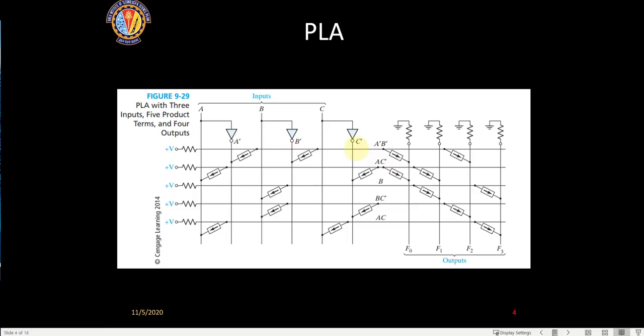So aren't the NOT gates supposed to be single direction flow, and the current can't flow in the opposite direction back towards A? Like, the current can't drop across it in the reverse direction? No. If you have seen a CMOS gate, all CMOS gates will be a PMOS followed by an NMOS at the bottom. So it can sink current. There is no issue. It can draw current. There will be a ground there.